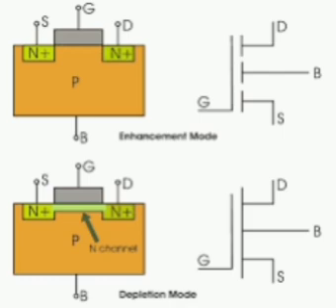Gate capacitance is given by C gate equal to Cox into W into L, where Cox equal to 3.45 into 10 power minus 11 by Tox. C gate means gate capacitance. W, L means width and length of gate plate. Tox means oxide layer thickness. Cox means oxide capacitance. MOS capacitor can be operated in 3 modes: accumulation, depletion, inversion.